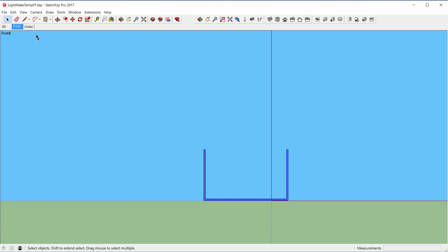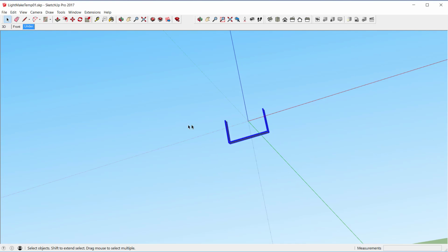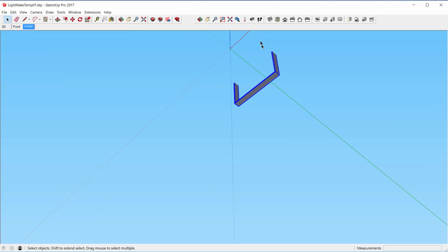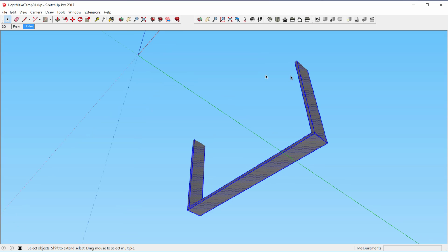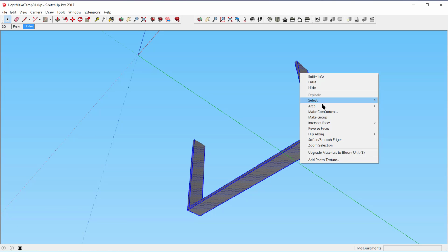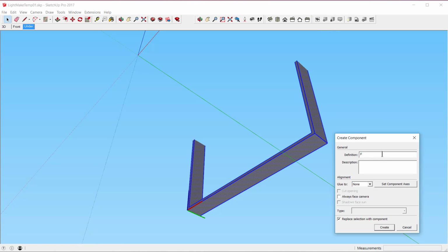Then we move the camera to view the mounting bracket from the underside to help us more easily set the mounting insert and azimuth rotation point. We now select all the visible surfaces and create a new SketchUp component which we will call FLD3011 base. Next, we select Any for the Glue To option to make sure that this mounting bracket will correctly snap onto any surface in our SketchUp scenes.